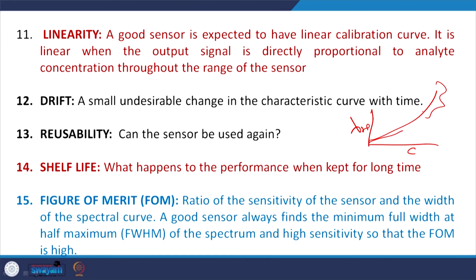If you report the sensitivity of a sensor, you want it to be constant, I told you that this is the slope. So, you want to have a constant sensitivity, that is the linear part of this response. That is what most people are concerned about, because you want constant sensitivity, then it is a good calibration curve. So, better the linearity, better the sensor.